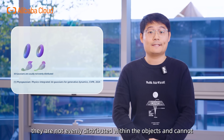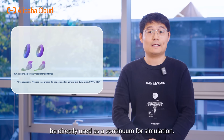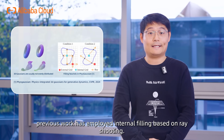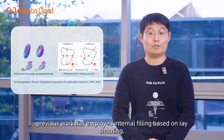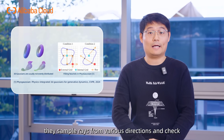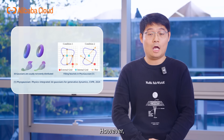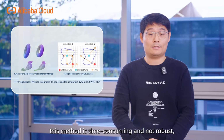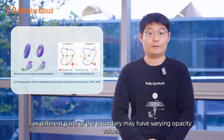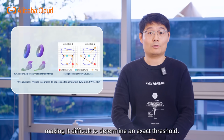In other words, they are not evenly distributed within the objects and cannot be directly used as a continuum for simulation. Therefore, previous work has employed internal filling based on ray shooting. Essentially, they sample rays from various directions and check if the rays intersect the high opacity boundary of the object. However, this method is time-consuming and not robust, as different parts of the boundary may have varying opacity values, making it difficult to determine an exact threshold.